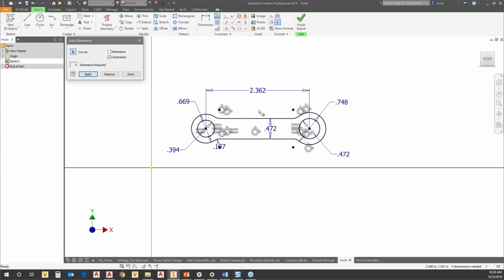And those I could just start applying by looking at some of the missing numbers. But I can see here tangent, tangent, parallel, parallel. It picked up as many of those as we could. Okay. Now, if I now check the dimensions, it's going to add some other dimensions. Keep in mind, this is not centered, right? You might want to add some more geometric constraints to fully center this, best practice again, right? But it might not dimension it the way you would. So I'm going to go ahead and now select this and get the rest of these 4 dimensions in.